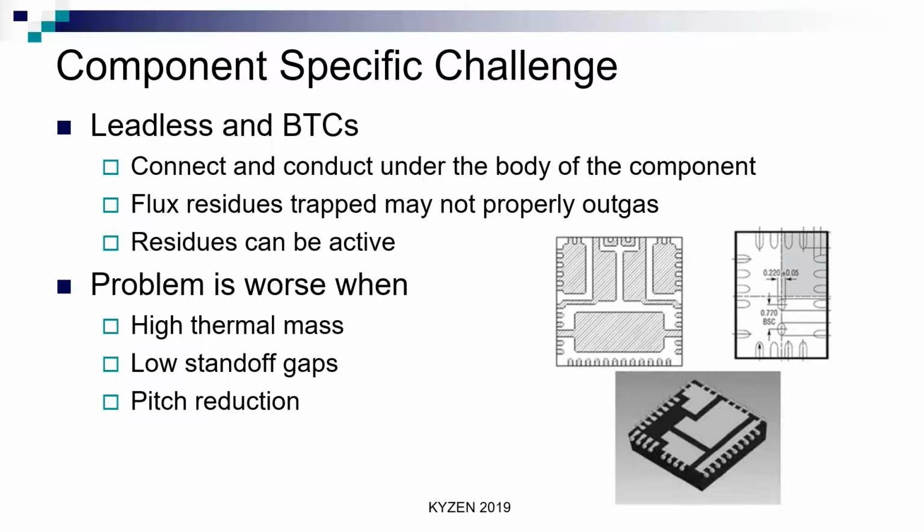With electrochemical reliability now, the concern is more of a component-specific challenge because of leadless devices and BTCs, or bottom termination components, where the flux is trapped underneath and may not properly outgas. What do we mean by outgas? We'll talk about that in a second. Hopefully we have a video that may play here. Those residues, those ionic species, may not fully activate.